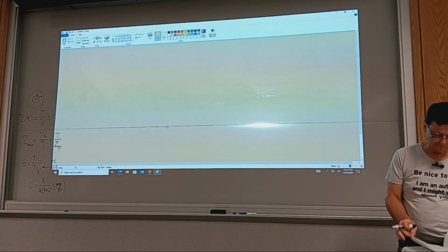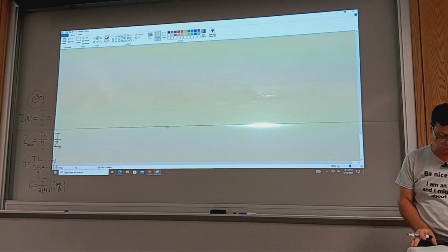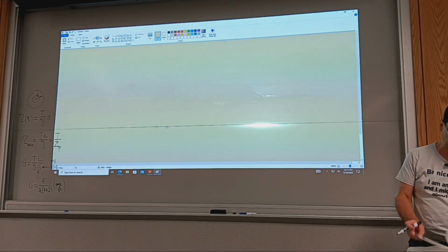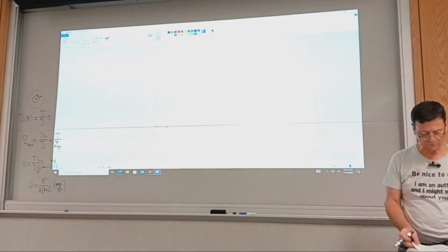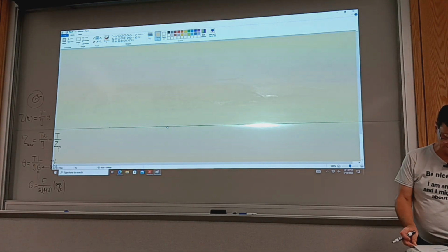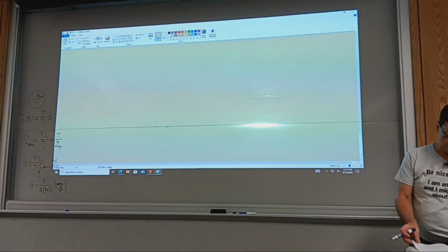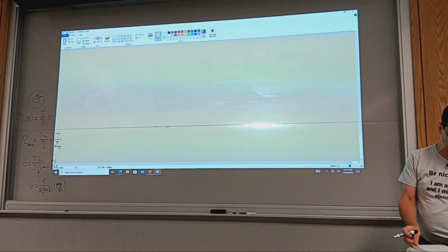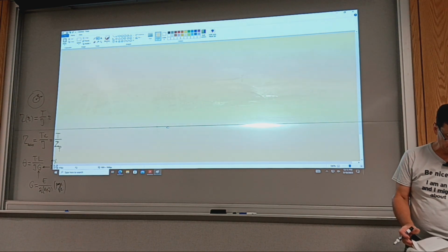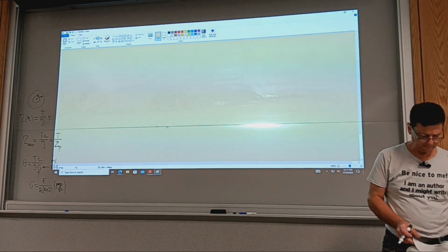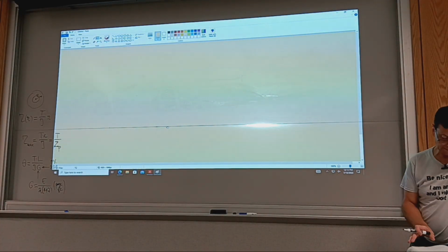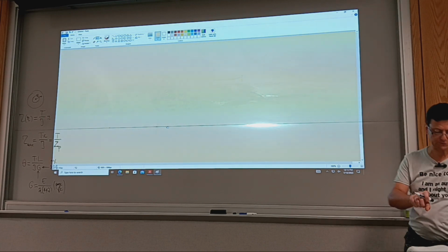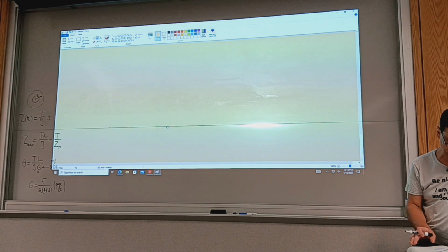Okay, so these are the equations that we'll be using over and over, and you'll see we're going to make use of them in the future in design of machine elements. And I'm not repeating the area or polar moment of inertia equations because they are in appendix 1. And the formula for direct shear, you just divide. It could be double shear, but in essence, you take the force that shears the member and divide it by the area, which gets you the direct shear stress.